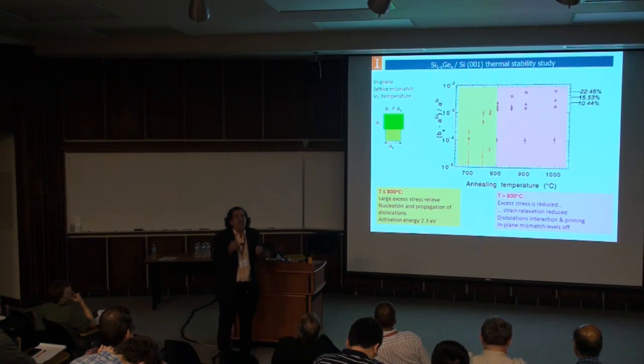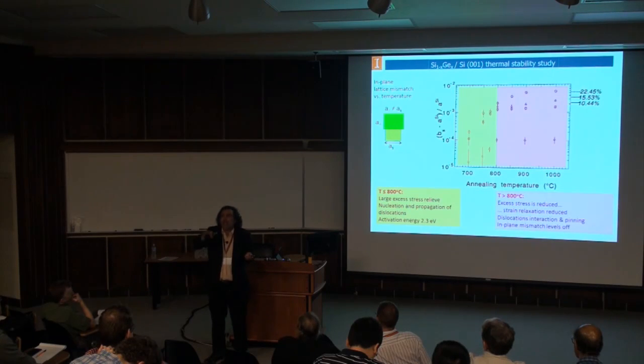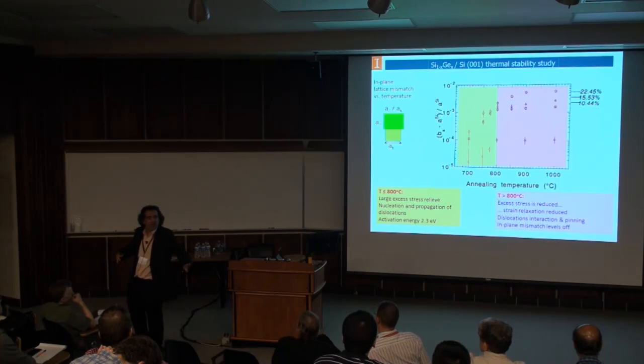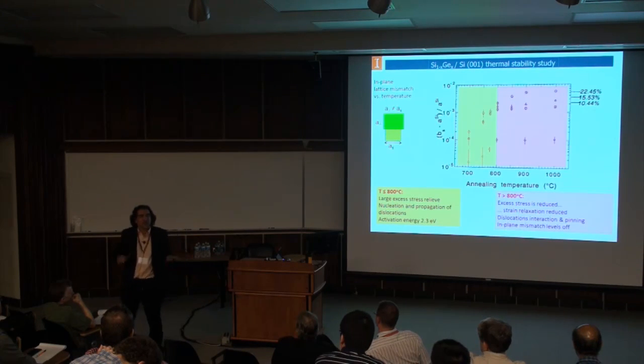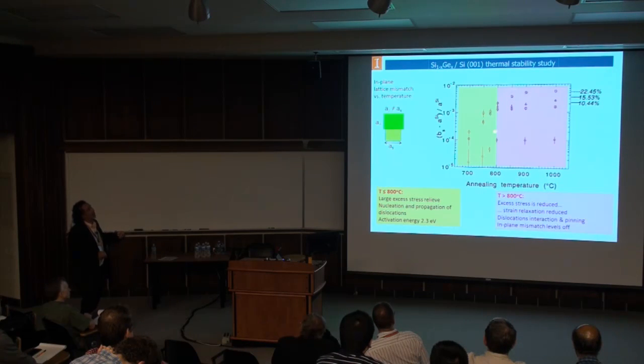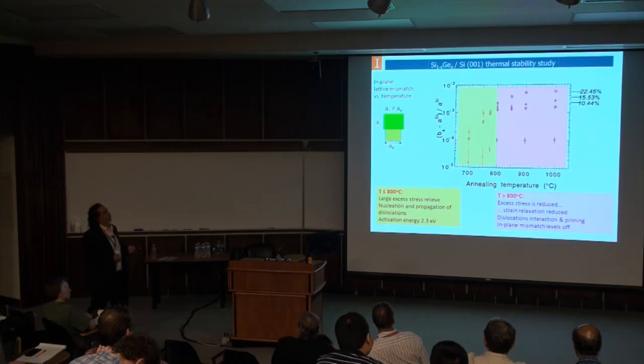Up to some point, it becomes very crowded. Like people going inside a bus, you cannot get more. So the dislocations start pinning each other. You cannot come here anymore because they were already here. So that's what they do. So the rate of defect formation becomes limited, and you can get all the kinetics at very high resolution there.